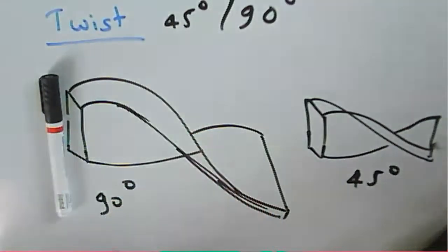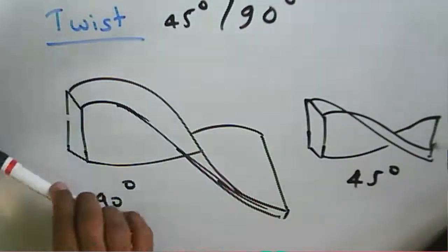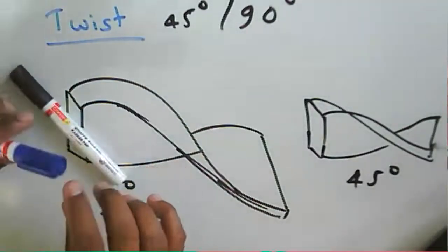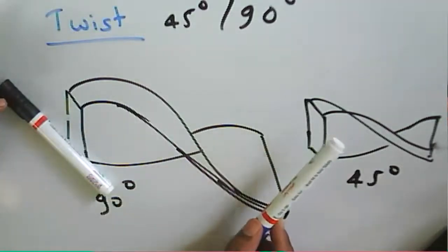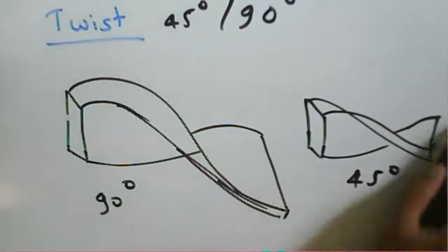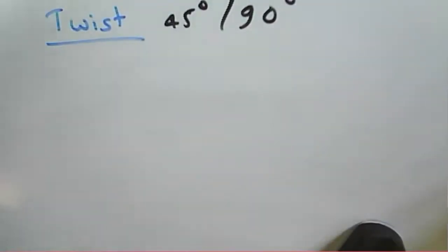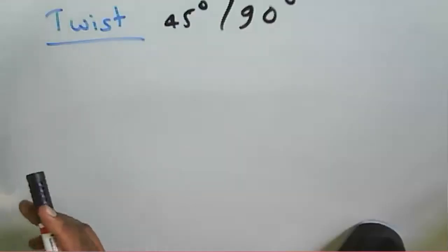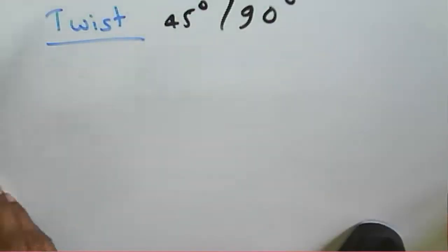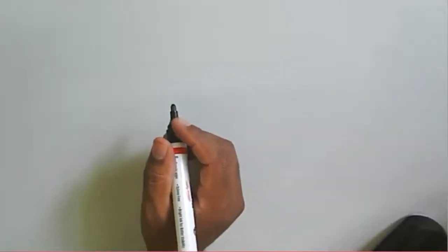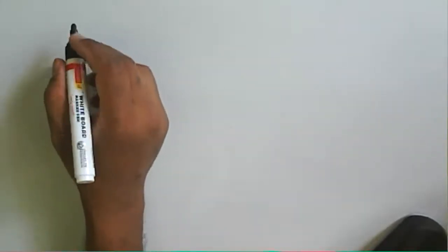So according to that, if you see here, the electric field component will change with a 90-degree twist. Polarization depends upon the field component, so converting vertical to horizontal polarization or horizontal to vertical polarization, we use a twist. Or at particular junctions, we require to change the position of the polarization. In that case, we use a twist there.